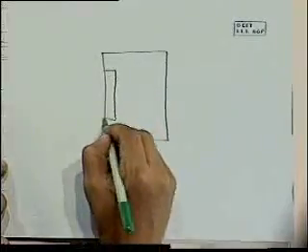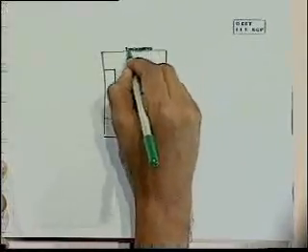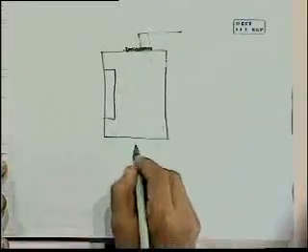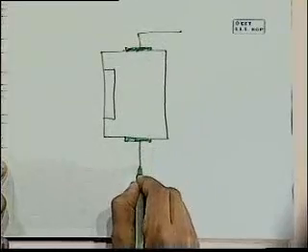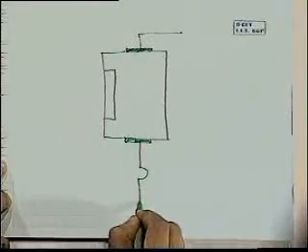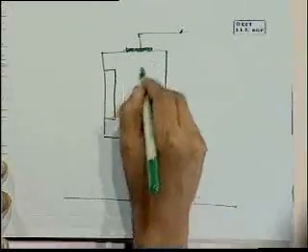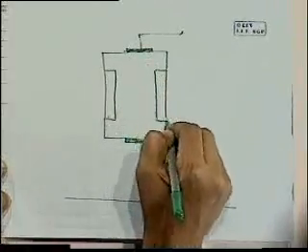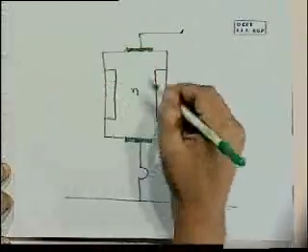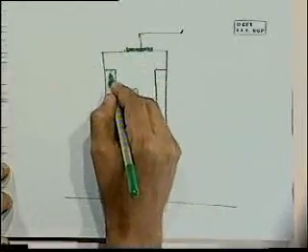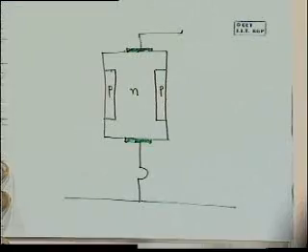You have the drain, which is connected through some metal contact, and you have the source, again connected through some metal contact. Let's say in this case we're talking of an N-channel device, so the center part is N. Into an N-type silicon, we create P-type layers. Two P-type layers are diffused in.